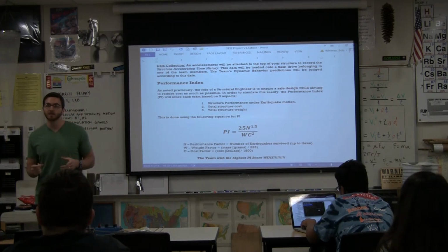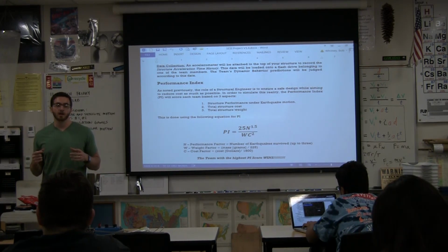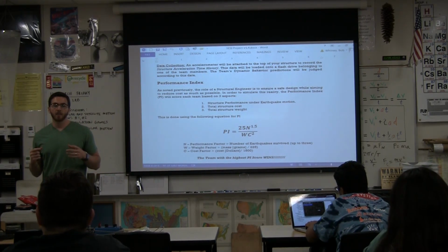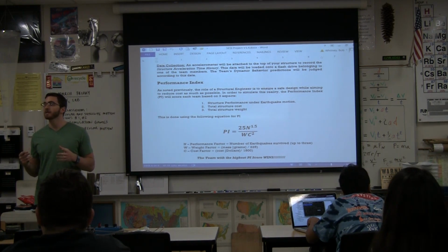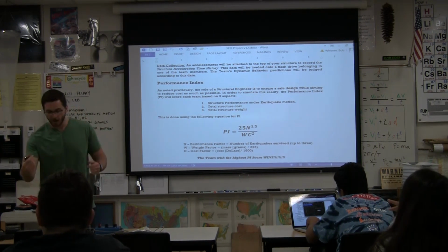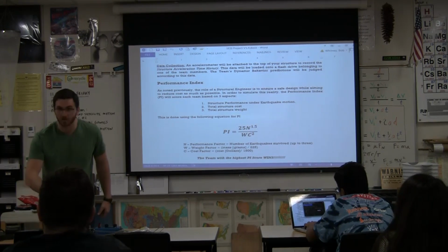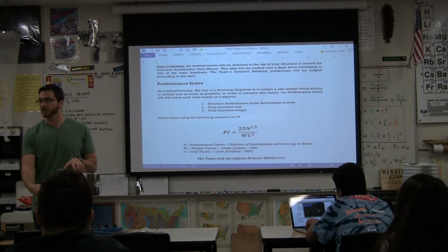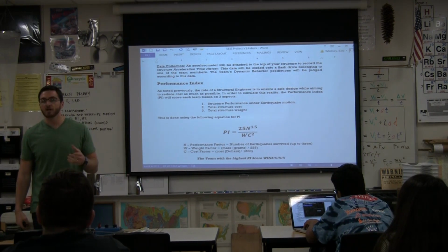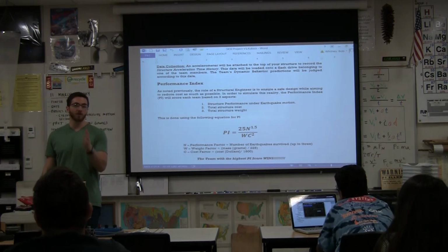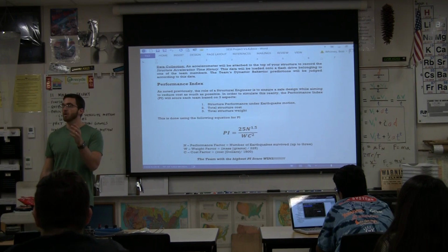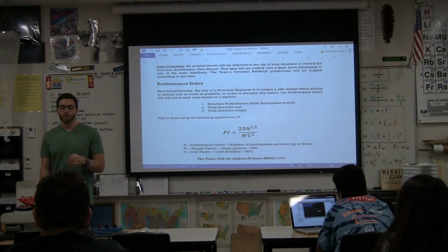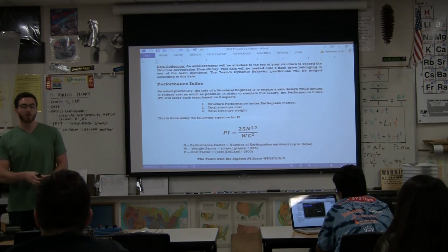And I gave you some hints, something about the brace frame. It doesn't have to be in every bay. So how many bays is in this structure? 4, right? If I look at it this way, there's 2 bays. You don't necessarily have to put a braced frame in every single bay, nor a shear wall in every single bay. The other thing that you guys can think about is we're only going to shake it in this direction.